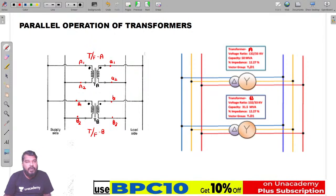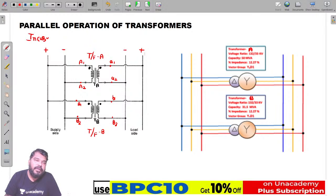So what it means: if we take this as the positive and negative supply, the load side also has a positive and negative supply. So what we conclude here is that the primary windings are connected to the common supply, and the secondary windings of the two transformers are connected to the common load. This is in the case of single phase transformers. Okay, all of you got my point?